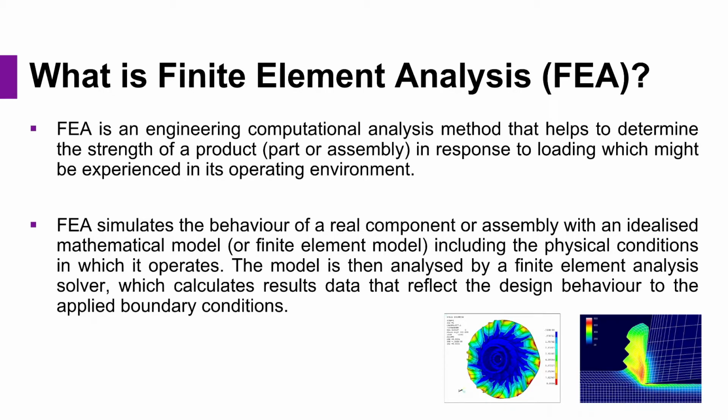So basically, FEA simulates the behavior of a real component or assembly with an idealized mathematical model, which we call the finite elements model or FEM, which includes the physical conditions that a part of the product is going to operate in. In this method, we analyze the model with the finite elements analysis solver, which is the main core, the main brain of the computer, to use the mathematical calculations and show us the result of how our product is going to perform in the boundary conditions that we make.